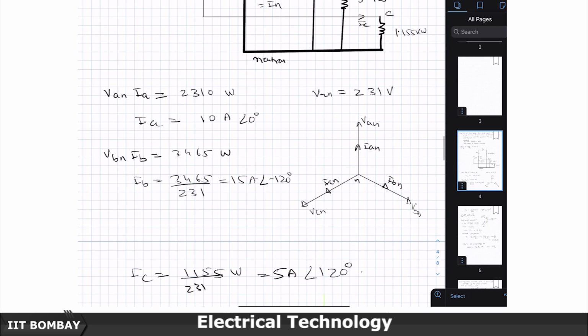So, this neutral current, see, the moment you have got this unbalanced thing, this neutral current will flow through the neutral wire. Neutral wire has a resistance. It may be either equally thick as the phase conductor, if you are expecting an unbalanced supply, or normally it is thinner also. If it is thinner, then the resistance will be more, and then it will suffer from I square R loss.